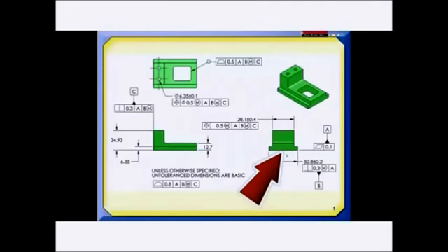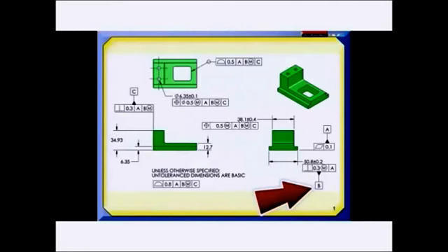My secondary datum feature is this width, B. Its size is 50.8 plus or minus 0.2, so the largest it can be is 51. And at 51, it can be out of perpendicular 0.3, so it can act like 51.3. In other words, its maximum material boundary with respect to the first datum plane would be 51.3. So if I build a fixture to hold this part, I would have two parallel planes 51.3 millimeters apart.